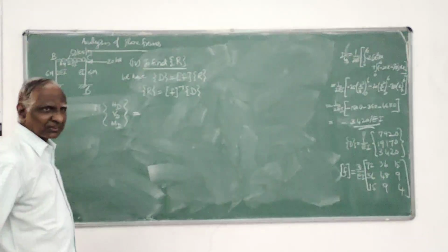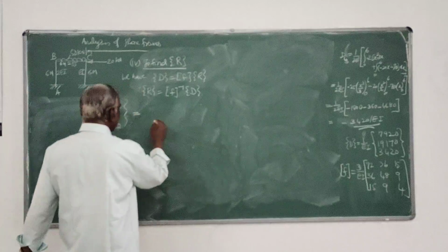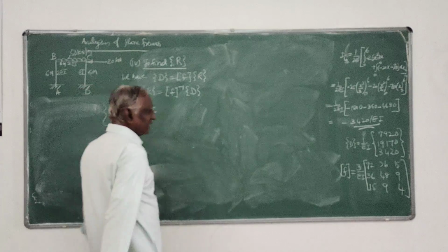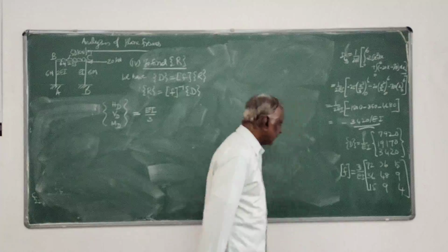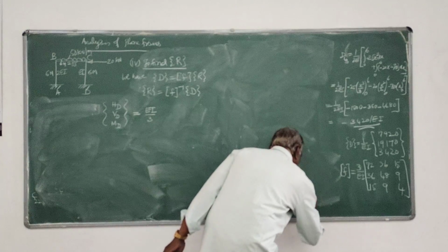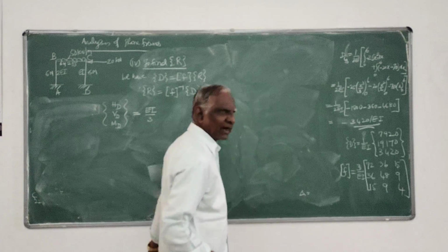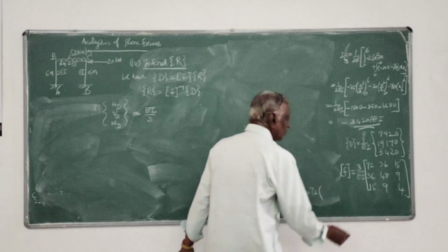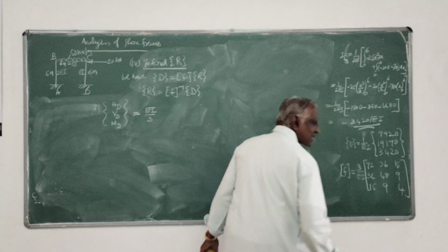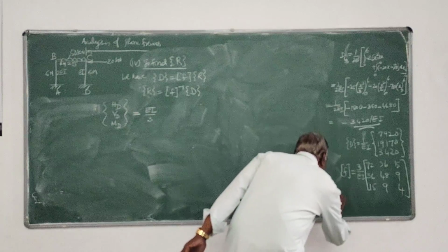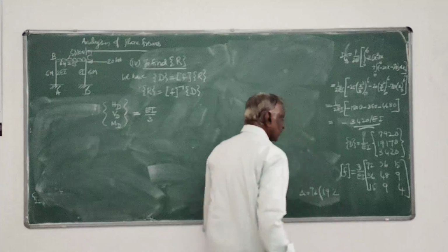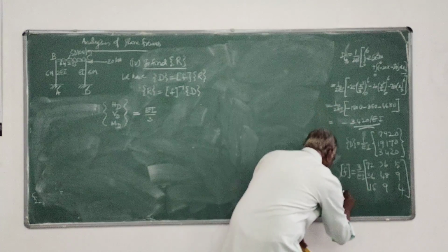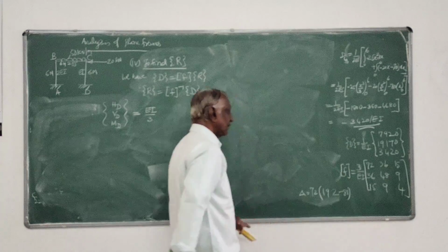So you have to find out F inverse. So that is 3 by EI, it becomes EI by 3. Then you have to evaluate this determinant. So the determinant delta is nothing but this 72 into 48 into 4 minus 9 into 9. 192, 48 into 4. Then minus 9 into 9, 81. So 111.